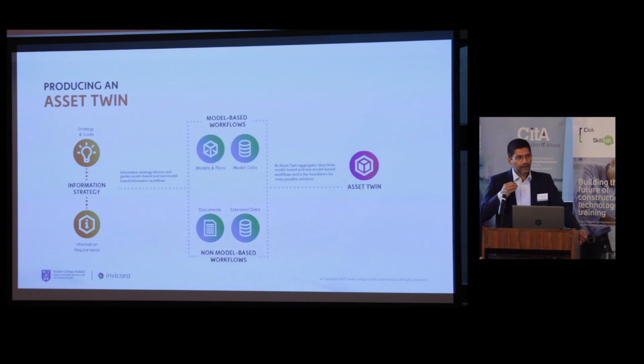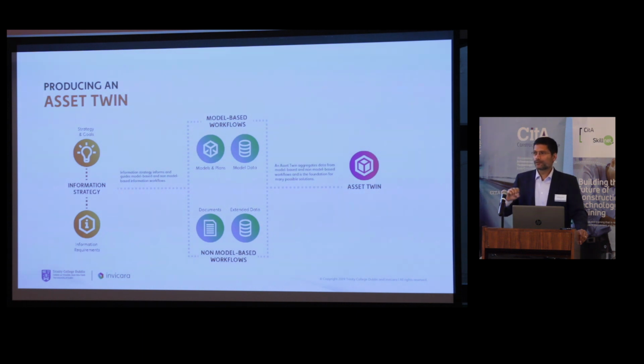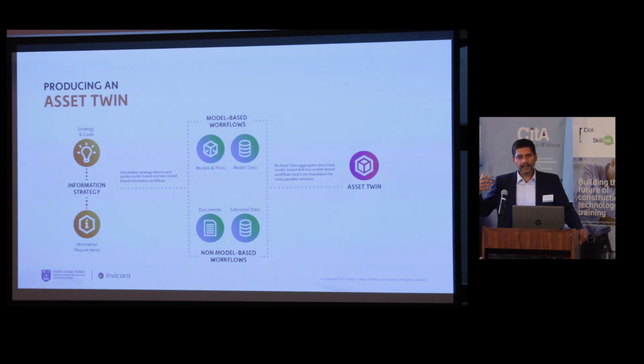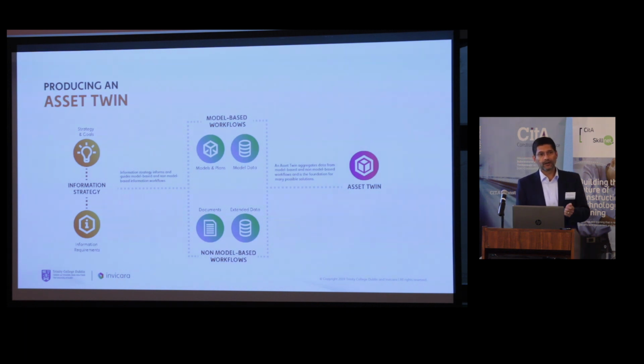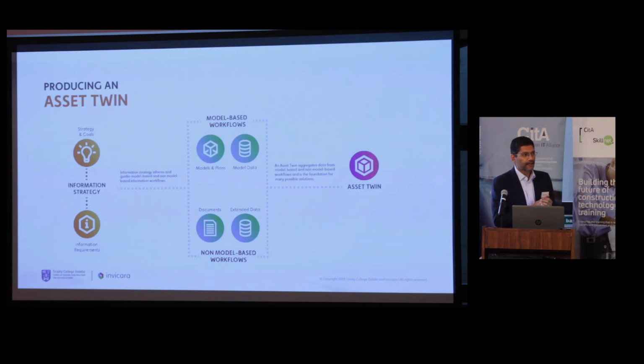Now, it's therefore really important to have the model-based workflows defined around the minimum data sets that we need to have from the model, which is what we discussed earlier, which is what is it and where is it. Once we have that, we can then collect information relating to those assets during the normal progression of the construction process from the right stakeholders. It could be delivered through custom web forms. I'm commissioning a piece of equipment, I scan an RFID device or a QR code, a form pops up and I enter the values and that data goes and links back to the model element.